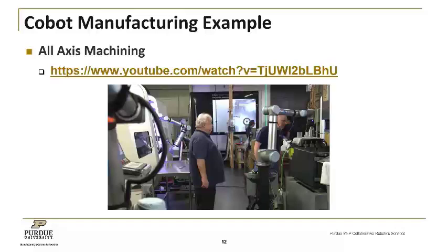They also saw their quality improve because the robots are consistently accurate in terms of how they perform their task. Whereas with a person, their attention can wander while they're working the production line. Their muscles can get fatigued, so if they're doing a drilling operation or a screwdriving operation, they're not pushing in with the same amount of force at the end of the shift as they were at the start of the shift. So there are a lot of benefits there for improved quality.